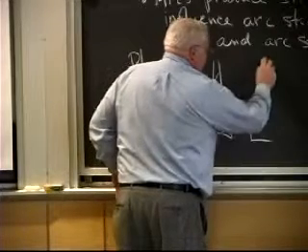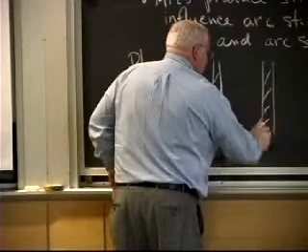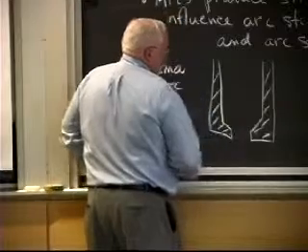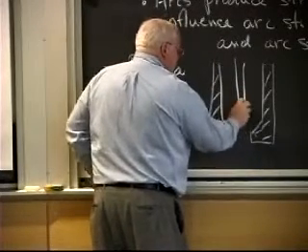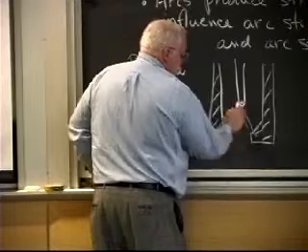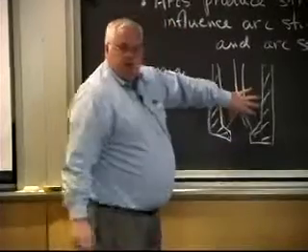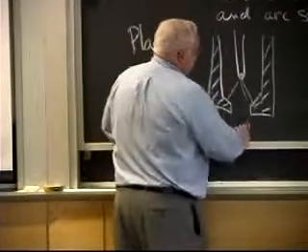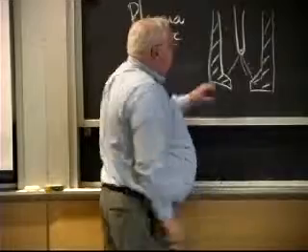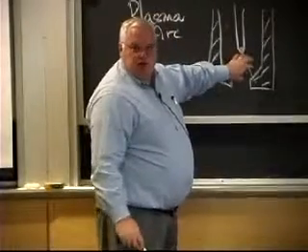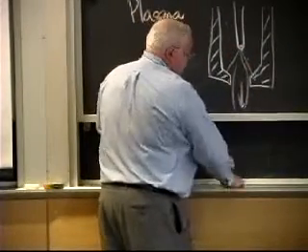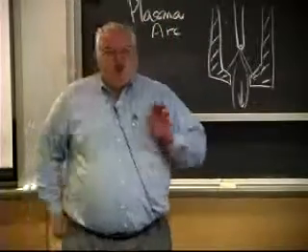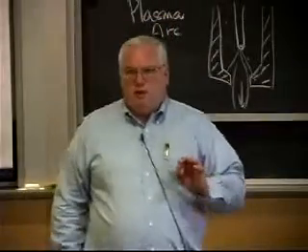It has a copper chamber, water-cooled or air-cooled, and a tungsten electrode that strikes an arc inside this constant volume chamber. Just like for a jet burner, if you do all your expansion at constant volume, you get a tremendous jet shooting out.